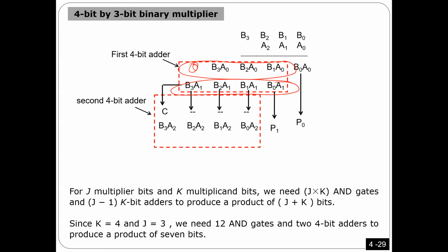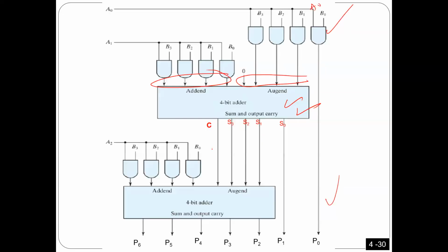Okay. And then look here. The first one here will be part of the output. But the other outputs here will be input to the second 4-bit adder to add them here. That's exactly what I did. So here the first one will be B2. I'm done with this one. However, the other 4 bits, including the carry here, will be the input for the second one to add.